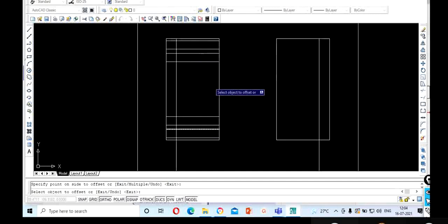This you have to continue till all the 4 coils are placed, 4 HV and 4 LV. First LV winding, insulation, HV winding, insulation, again LV winding. So LV and HV have to be placed alternatively with the insulation in between.